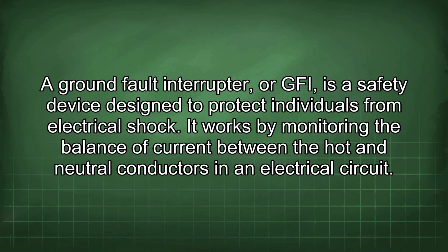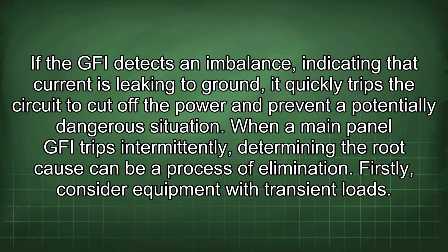A ground fault interrupter, or GFI, is a safety device designed to protect individuals from electrical shock. It works by monitoring the balance of current between the hot and neutral conductors in an electrical circuit. If the GFI detects an imbalance, indicating that current is leaking to ground, it quickly trips the circuit to cut off the power and prevent a potentially dangerous situation.